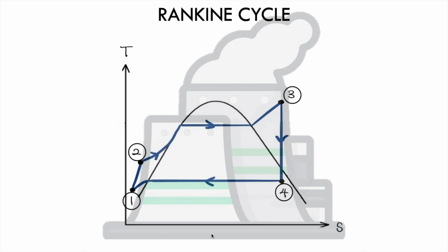In ideal Rankine cycle, water at stage 1 should be in saturated liquid. However, in actual application, maintaining the temperature of the water to be constant throughout the condenser might pose a challenge, as higher rate of heat transfer between the coolant and the working fluid would contribute to the temperature drop across the condenser. Through application of Rankine cycle, we can actually improve the thermal efficiency of the nuclear power plant by manipulating some variables in the cycle.